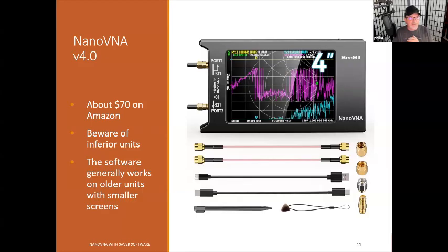You can see there's a whole bunch of accessories there. Some plugs to plug everything in. But the most important things are going to be these, you can see them there on the right. These 3 little calibration things. And we are going to calibrate the unit. You'll have an open one. When you look in the bottom of them, I don't think it'll show up on screen. Yeah, it won't. Okay, so there's one of them that has the little pin in there, or nipple, whatever you want to call it. That's the closed. There's one that doesn't, that's the open, and the silver one is 50 ohms. If you're familiar with a Smith chart, then you've got a 50 ohm point, a closed point, and an open point to calibrate the device.